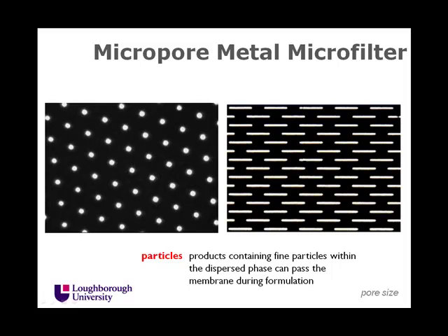And likewise here, for filtration we normally use slots, and this one here could be a slot of say 4 microns diameter, something like 400 microns length, and again it's all uniform, all the same size, and straight through. There's no depth, there's no sponge-like network behind the opening, behind the pore.